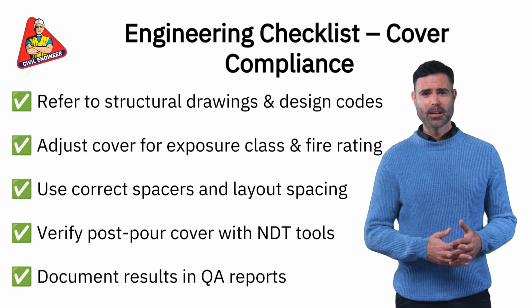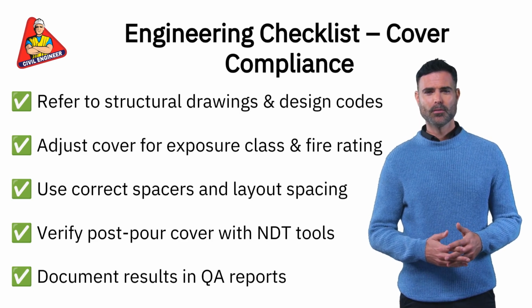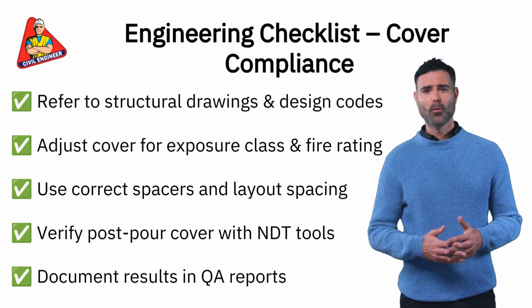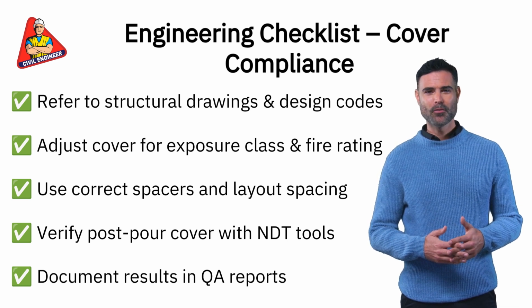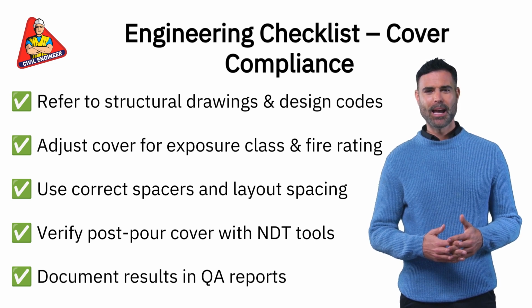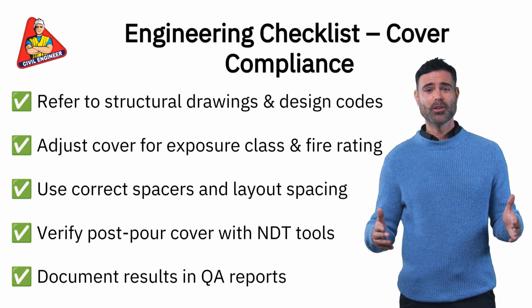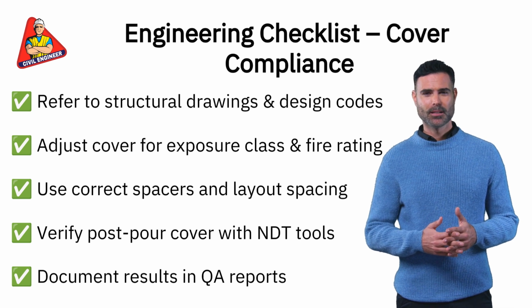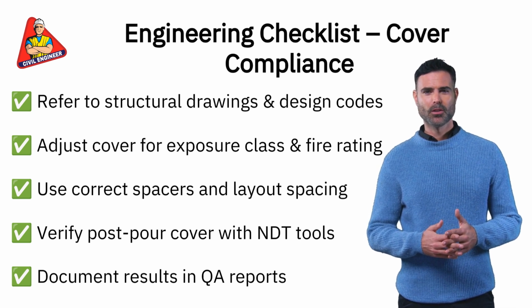To ensure concrete cover compliance, always refer to code-specific tables and approved drawings. Increase cover where required by exposure conditions or fire rating. Use standardized spacers or cover blocks. Post-pour inspections must verify as-built cover. Record all checks as part of your project QA process. Proper cover design and execution are cost-effective methods to extend service life and avoid early structural distress.